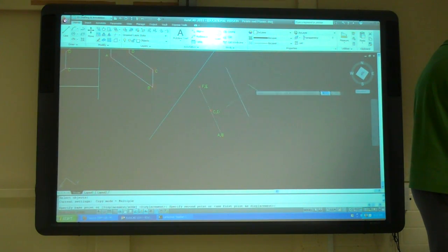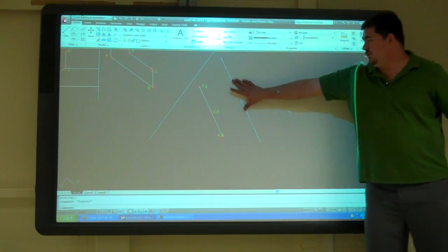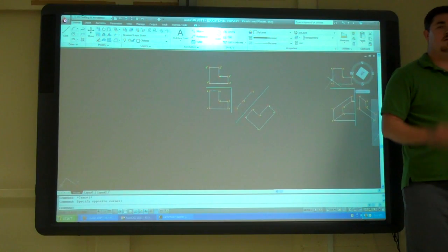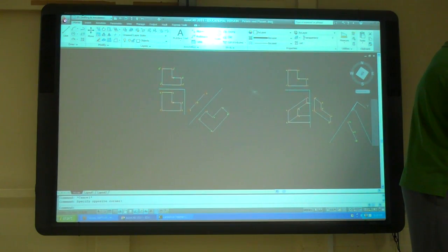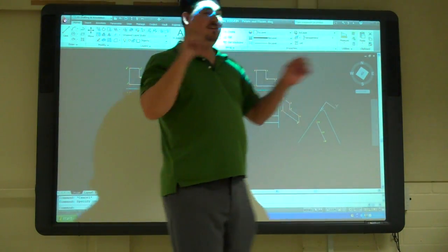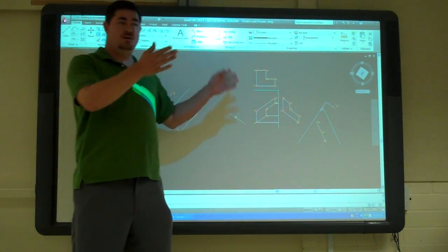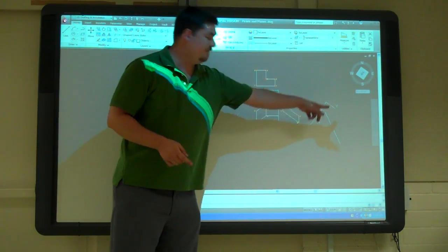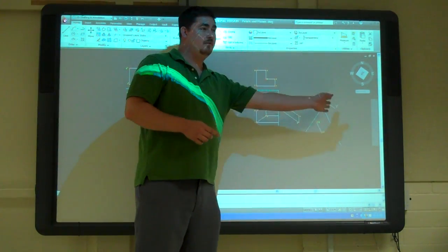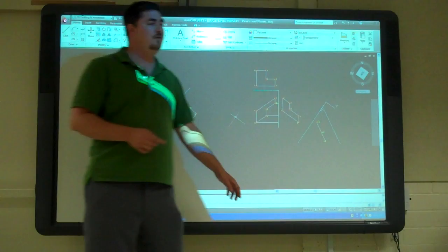Right, I can copy that over. Make a floating line there. And now do here exactly what we did here. Does that make sense? That's why we spend so much time on the basics of projecting, measuring 2 views back. Because now I've gone from 3 views to 5 views now. And that's just looking at different ways to get to a true shape view.